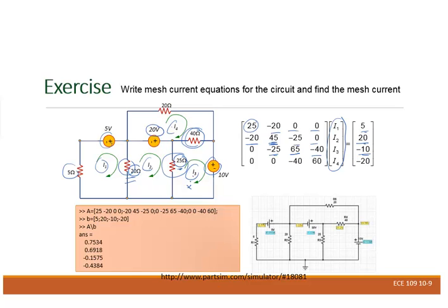When you write I4, same way, I4 and I1 there is no relation, 0. I2 and I4 there is no resistance, that's why it's 0 right there. You can see I4 and I3 there is a negative 40 right there. So it will be here 20 plus 40 will be 60 I4. If you look at direction of the current selection, so positive 20 will be equal negative 20 the other side. So we have matrix form here. I want you to do exercise on this one again. We will go over one more time in the class.